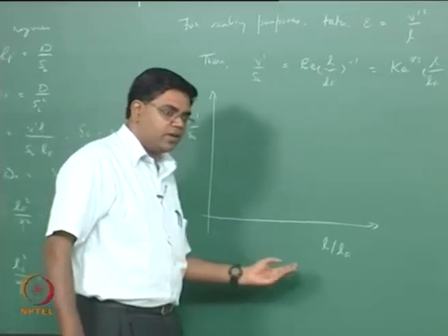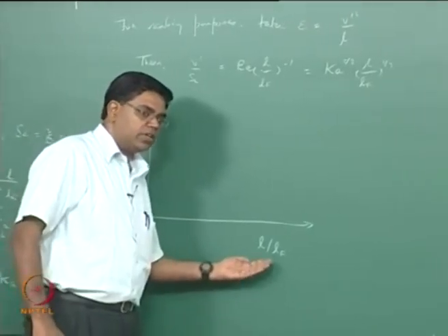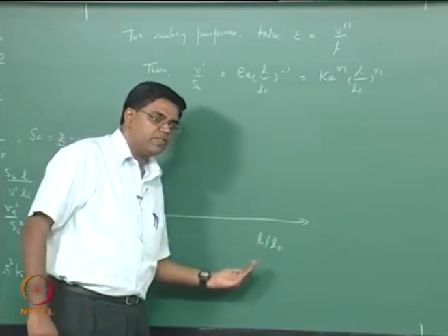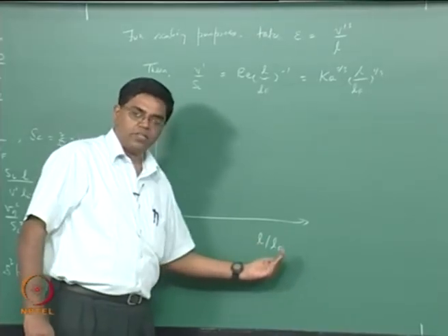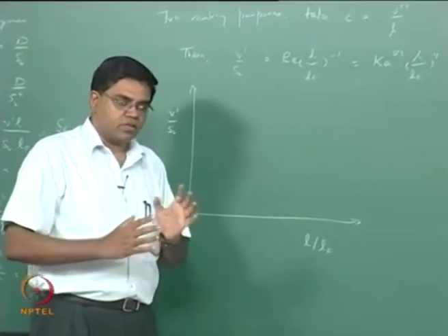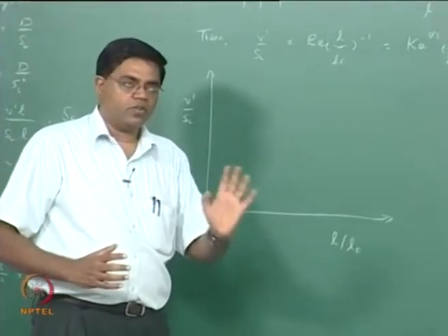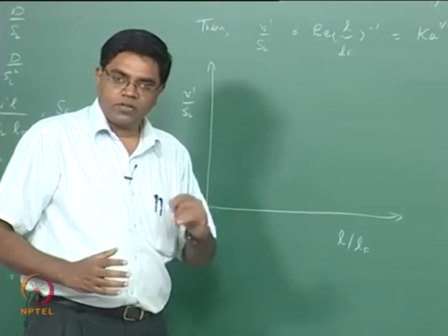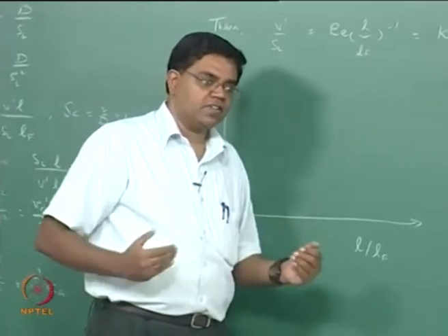That means we are saying, can we look at the turbulent length scales in comparison with the flame length scale, like the flame thickness. So are we having typical eddy sizes that are bigger than or smaller than the flame thickness. That is on the one side as far as the scales are concerned.